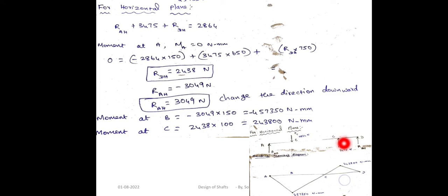Write that also. Okay. Now put the upward forces on one side and the downward forces on the other side. Next step, let us find the moment at point A. At point A, the moment value is 0. We know that. So 0 equals, what are the forces there?